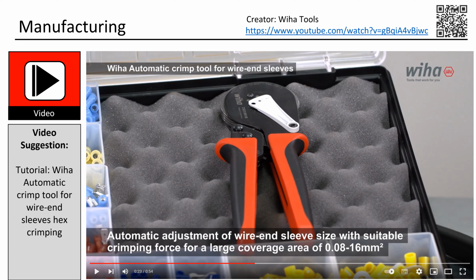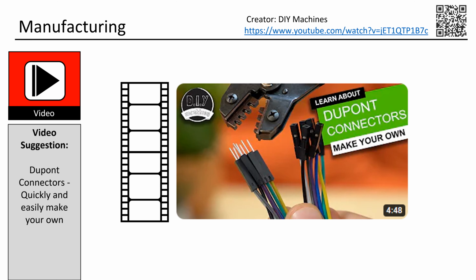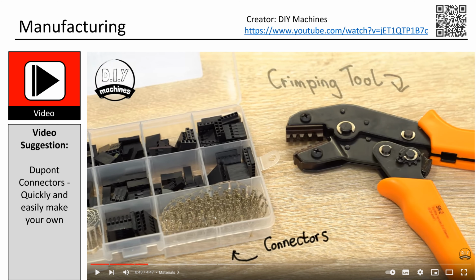If you use a connector that has no cage clamp, you always use wire end sleeves on your cables. When using these kind of cage clamp connectors, one uses just the stranded wires without wire end sleeves. These connectors are used in electronics and often in combination with a Raspberry Pi or an Arduino controller. They are great. You buy them as a set first. You have a special crimping tool and then can assemble the desired connectors. Very cheap way to create a connection.